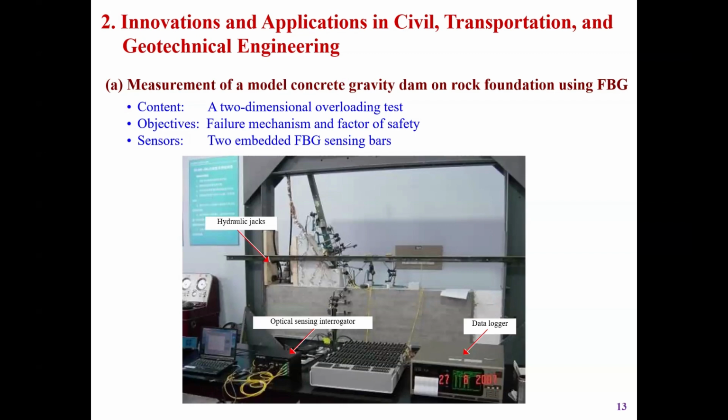This is the concrete dam and the foundations. This is a model test. My student did this more than 10 years ago. They use a hydraulic jet to simulate the water pressure to push the dam. The dam will have a deformation, and the foundation will have deformation. You can see there are many LVDTs to measure the lateral movement.